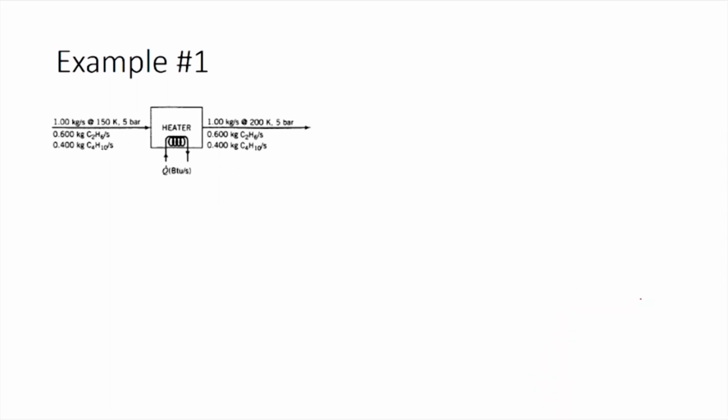So, this is an open system, which means the energy balance for this system would be ΔH dot plus ΔEk dot plus ΔEp dot equals Q dot minus Ws dot. For this system we have been asked to ignore kinetic and potential energies. So, these two will go to 0. There are actually no moving parts in the system like a piston or things like that. So, therefore, the shaft work would also be equal to 0. This means the equation is simplified as Q dot equals ΔH dot. So, the amount of energy which needs to be supplied in the form of heat would be equal to the change in enthalpy which would be seen for the system.